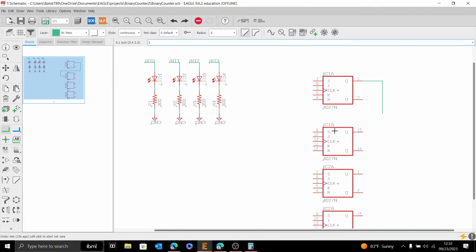And so that's why we're going to take the complement, so that when the Q goes low, the Q complement goes high, and that ripples down to the next bit. Does that semi make sense? At least seems logical enough that you can kind of follow. Any questions on that? You said it? Oh, okay.